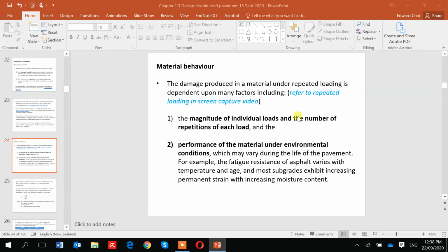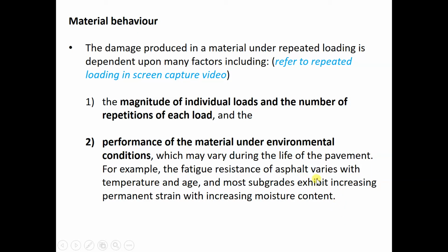Okay. So there's failure of material, especially for tensile loading. Under repetitive loading, the pavement layers undergoing tensile stress could fail because of the repetitive loading, by fatigue.